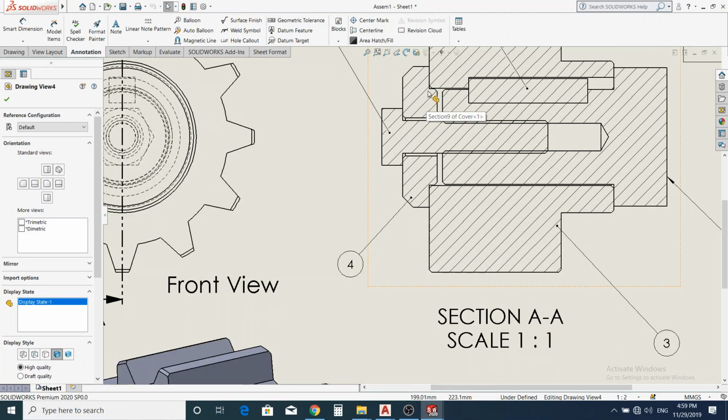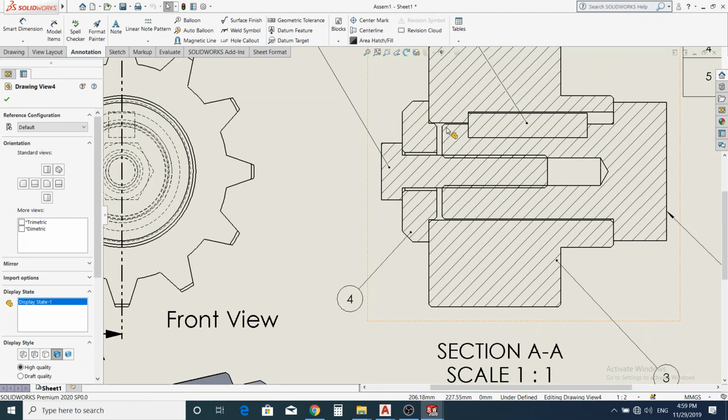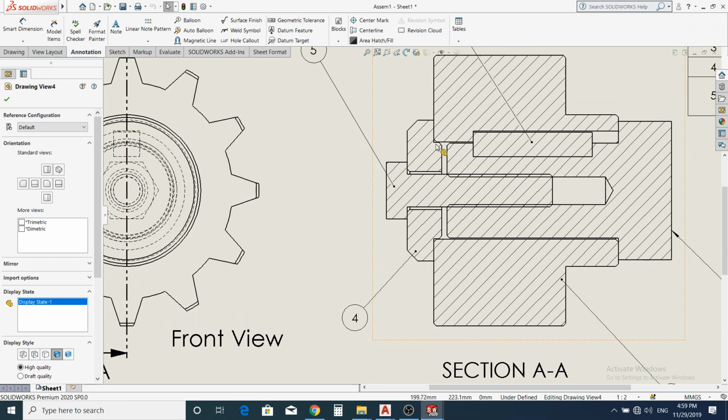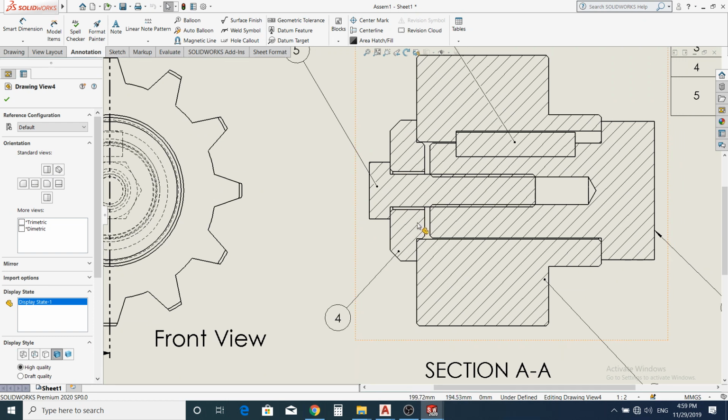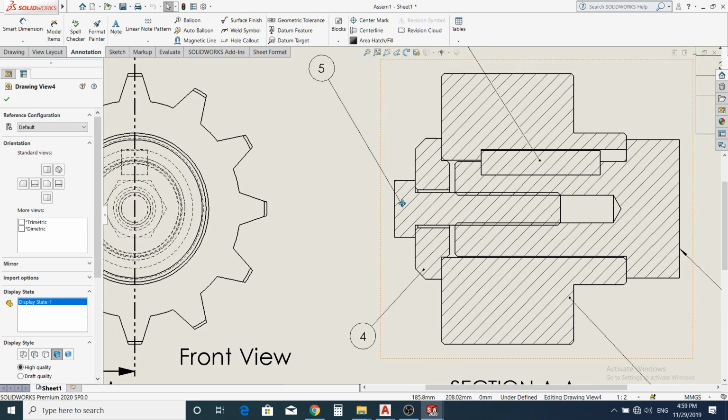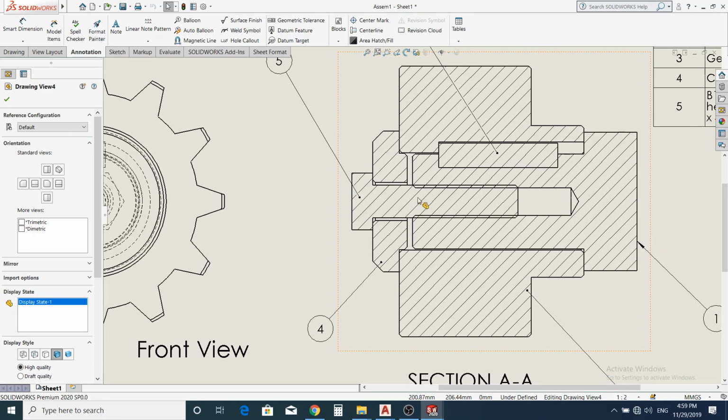I will machine the cover in this shape to restrict the movement of this gear in this direction. When I fit the cover in, that is not all. The gear can still come out. So now I used this M12 screw to secure the cover onto the gear together with the shaft.